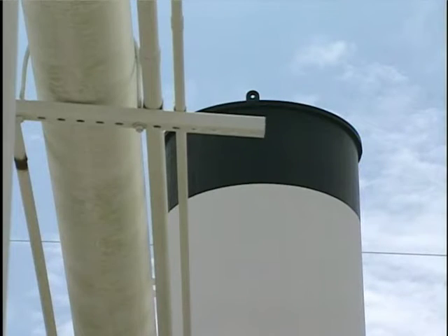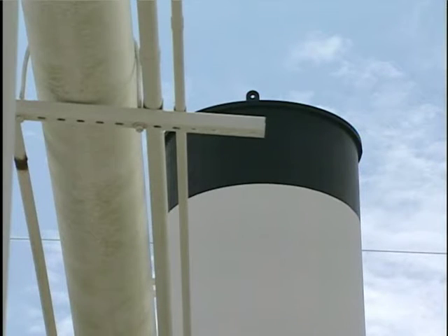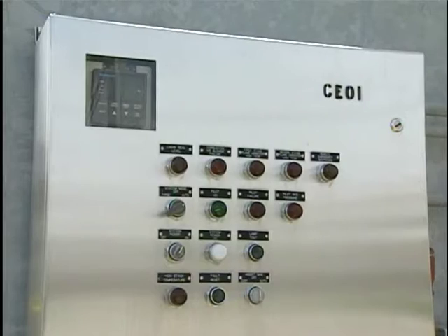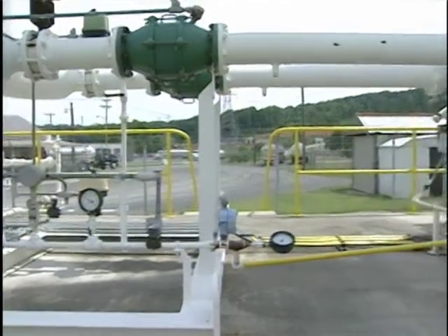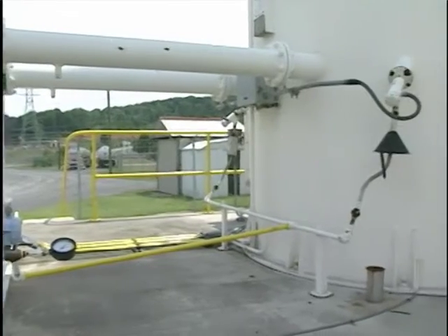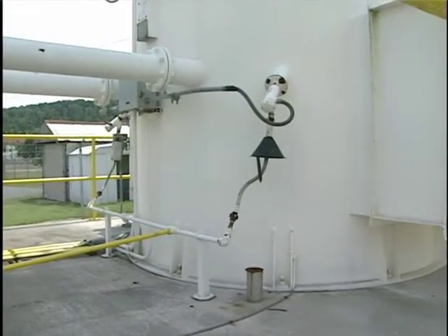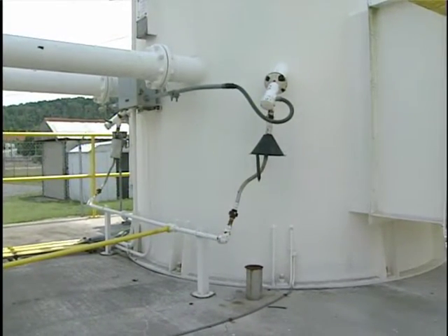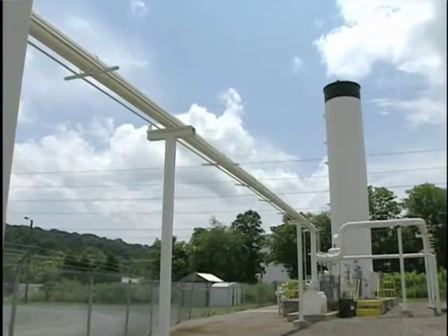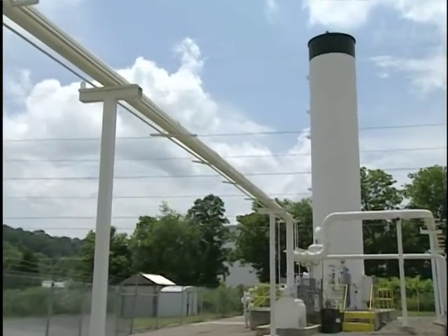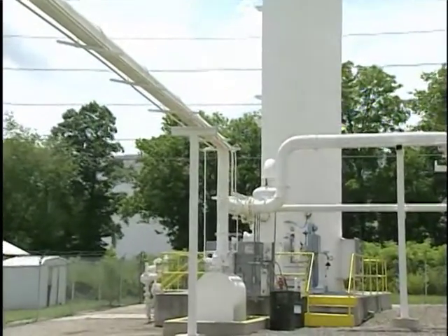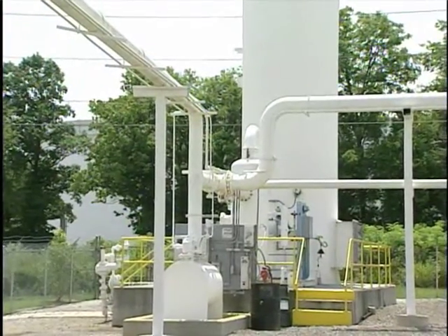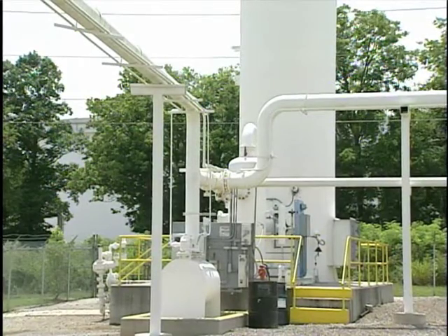Often, outlet concentration measurements required by regulation are based on calibrations with a reference gas. The instruments are calibrated using a readily available organic compound such as methane, propane, hexane, or 1,3-butadiene as specified by the applicable regulation. Under these conditions, the instruments will provide a measure of performance relative to a compliance limit expressed in units of the calibration compound or as carbon.